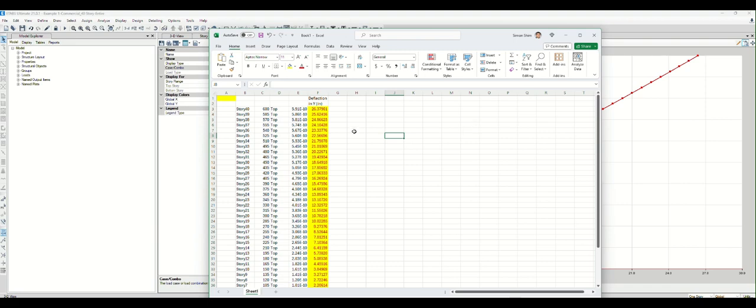We maybe want to stop or limit our wall thickness at some 24, 26 inches, because you don't want to keep increasing the wall thickness, because we're losing some leasable space. Continuously increasing thickness may also not be efficient because your moment arm is almost identical, but you're increasing the flange thickness. So we better think about other more efficient ways to increase the stiffness, which we're going to consider some outriggers later on. So this is the first step.